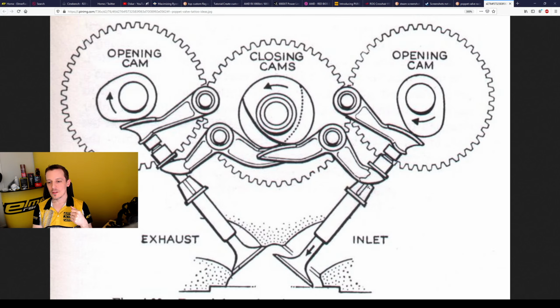And so yeah, I'm wondering how to introduce this. I don't think I have any really smart way to, but it's really a sort of optimization problem or design issue mostly. So when you really start pushing parts as far as they will go, you need to take their flexibility into account, because when you start getting into inertial limits, then the parts that you're using, like this rocker here, for instance, or this finger follower, or finger rocker, whatever they're called.